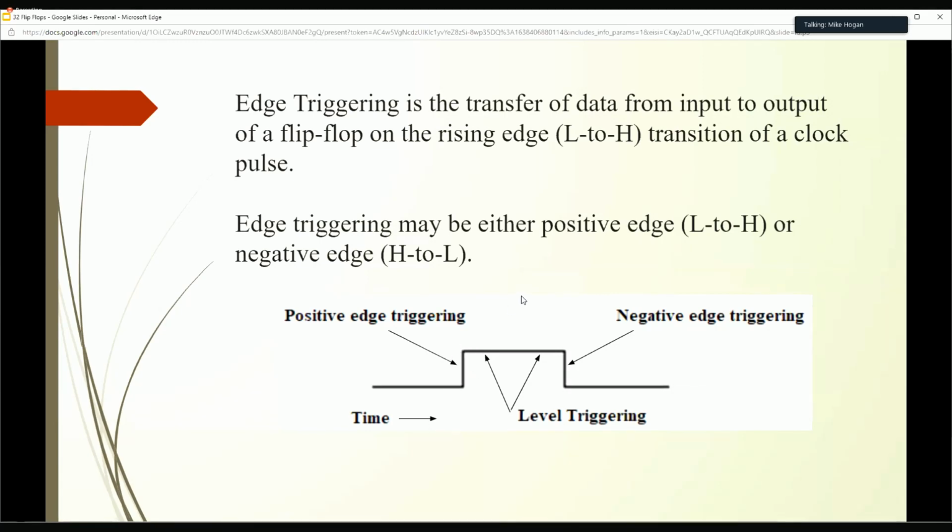When we have that up clock going from a low to a high, then we'll have our flip-flops trigger, and it will cause the actions that we're going to see really starting next slide, in terms of how these flip-flops are then going to hold a signal in place, if you will.